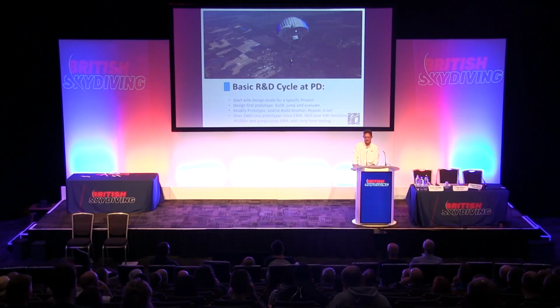And so somebody that might make 1,100 jumps a year will jump that parachute and send it back to us every 100 jumps. We'll look at it, measure the characteristics of the fabric, we'll jump it, compare it to a control sample that hasn't been jumped. And we'll keep doing that until the parachute has reached its life limit. And we really appreciate them doing that because it allows us to do the test jumping that's a little scarier, a little more creative.